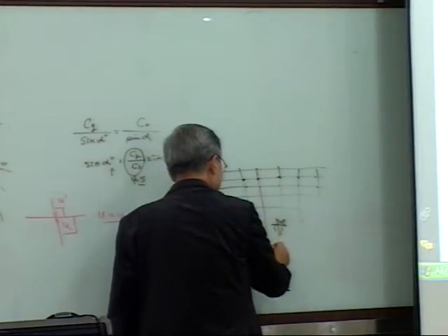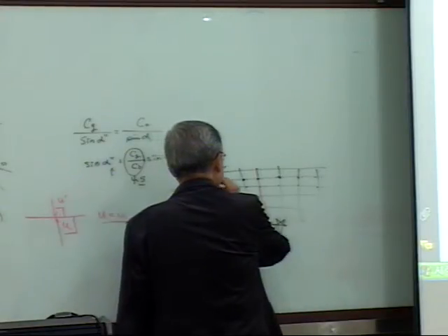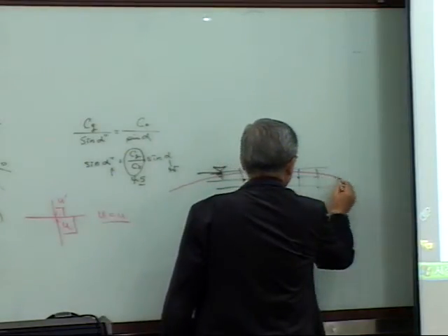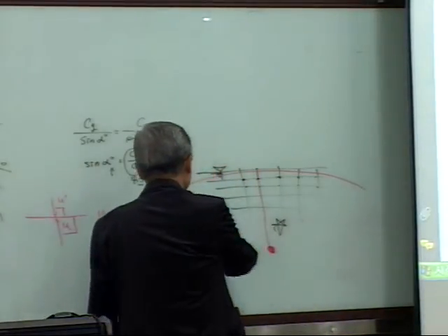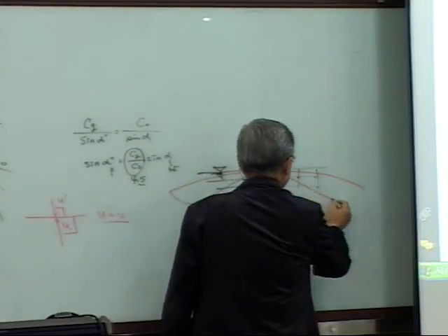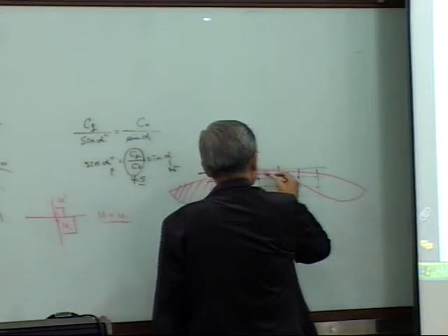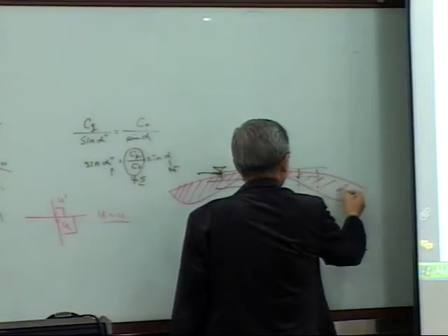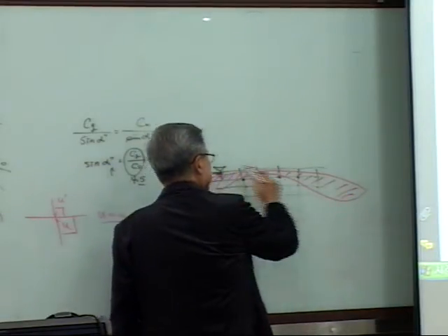Then if the charge is right there, you can draw the outline called the upper cavitation boundary. Then you also have to calculate the so-called lower cavitation boundary. Then you can declare the bulk cavitation zone. Okay? I exaggerate a little bit.